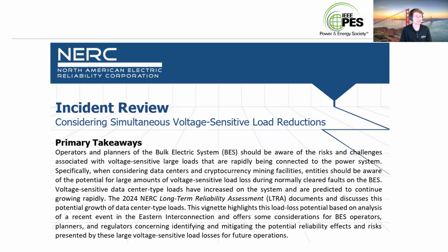I watched an ERCOT presentation last Friday. I don't know if I'm stealing this from Eric, but they did a fantastic study where they looked at the frequency stability limits and the voltage stability limits of a specific area of their system. They tried to use a low inertia case, something where there wasn't a lot of foot room, which is a kind of new idea: how much can your reserves regulate down. And they did find a specific megawatt limit.